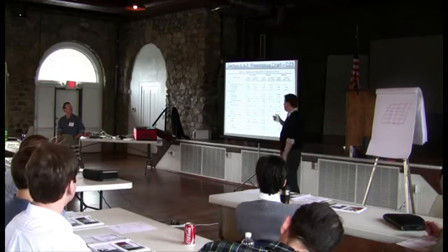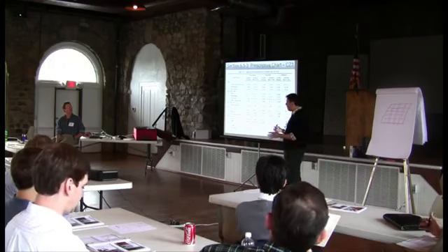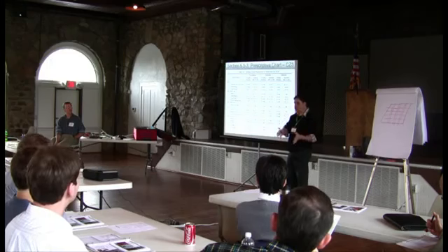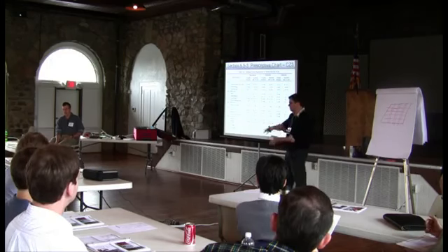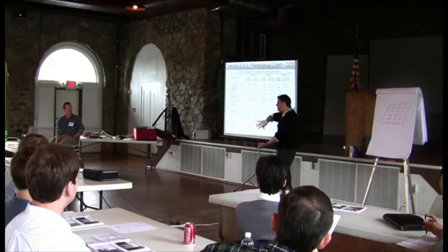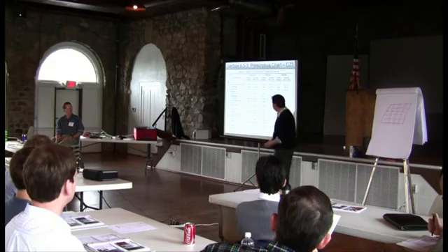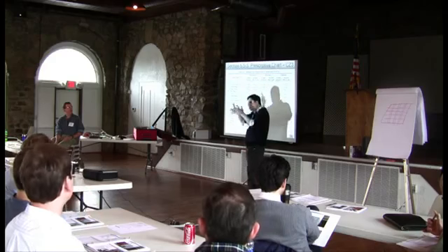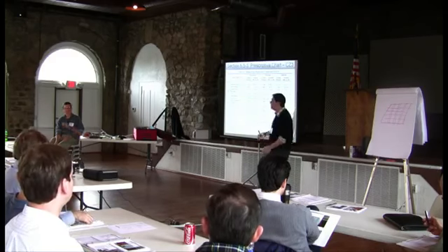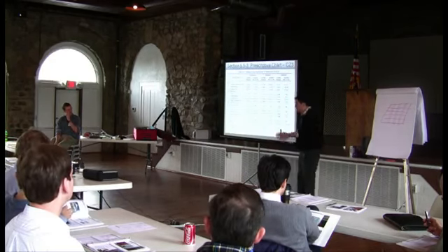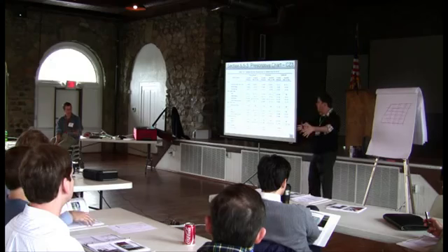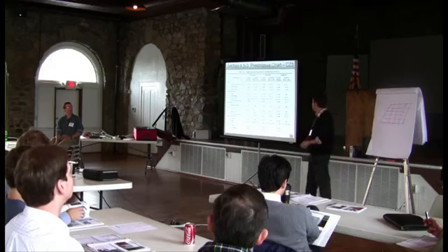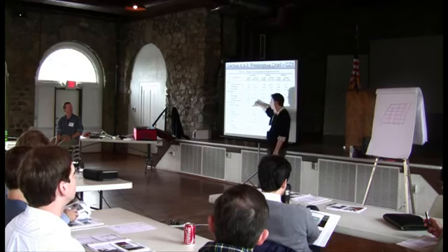And going back to some of the comments, I think there's two ways to do metal buildings. We can have the metal building where you've got the metal sheathing on the outside, the insulation, and then you sort of have a steel stud wall on the interior. That's going to fall under this metal building wall. That exterior component has to hit that R13. But if you move those steel studs out, and your sheathing sits on those as opposed to the purlins, it's going to fall under this steel framed.